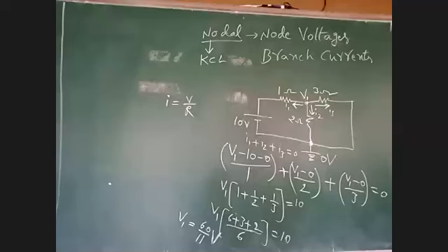But as a general convention, follow one thing in the entire subject, because we are not only dealing with nodal analysis. When you go for theorems also, if you mix incoming currents, you will be confused. If you want to take incoming currents throughout the semester, you have to follow incoming currents. I am following outgoing currents. Is it okay?